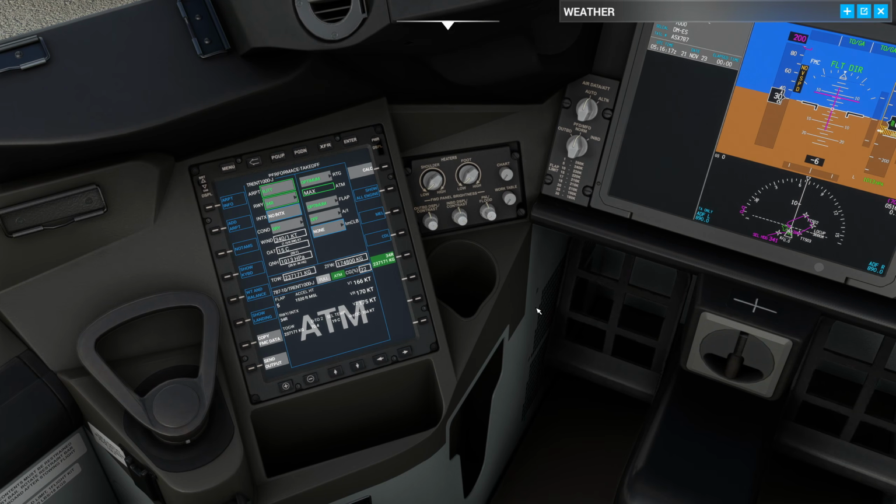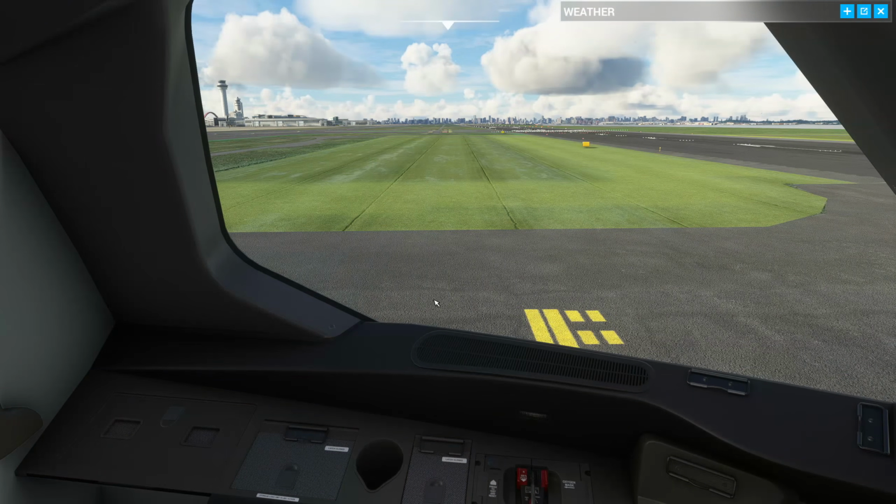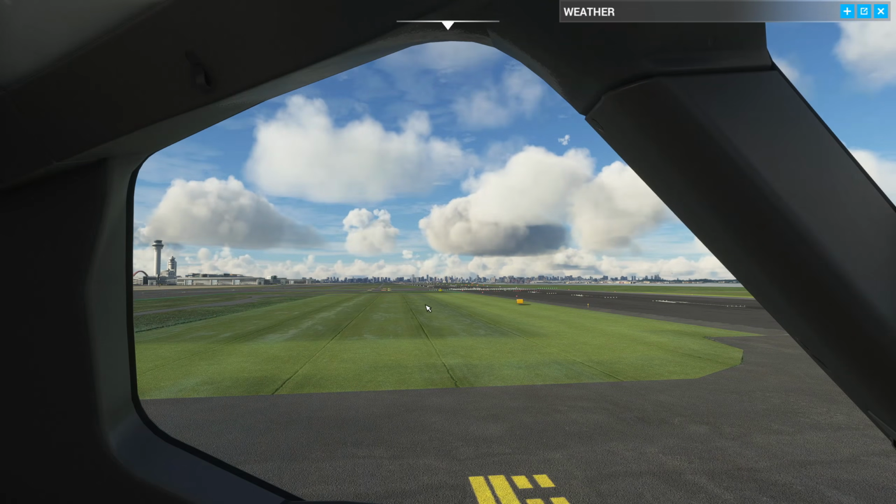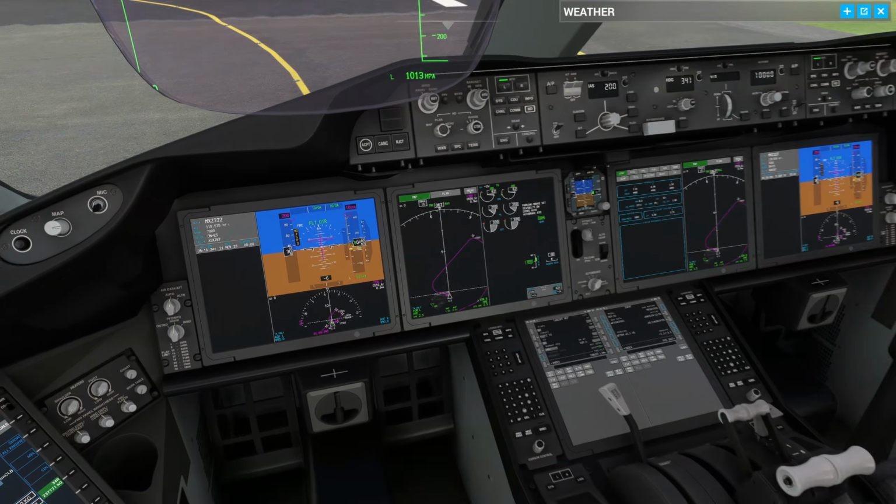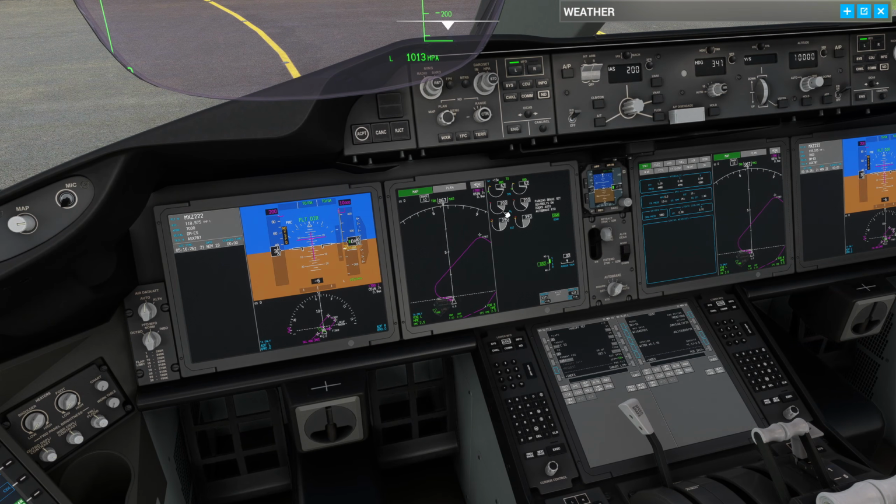The aeroplane actually has a system to counteract this, and this is why I wanted to do a specific takeoff tutorial. It has a system that will, if it senses you've gone too far on thrust on the live engine and the aeroplane can no longer maintain lateral control, actually remove power from the remaining live engine in order to keep the aircraft able to fly upright and pointing in the right direction. And Boeing says that if this system activates, so you've lost an engine and now your live engine is derating itself, it is better performance than if it didn't, which is a really remarkable thing.